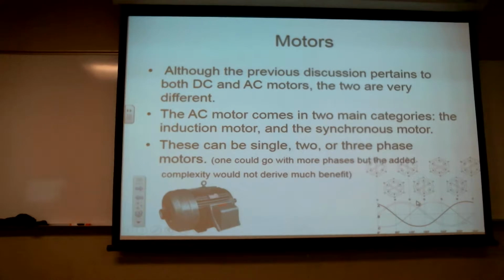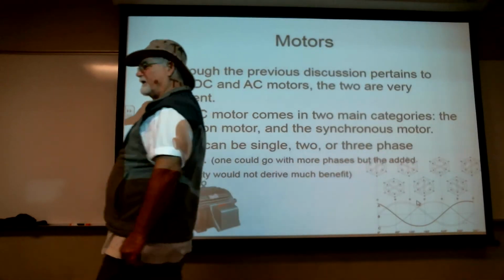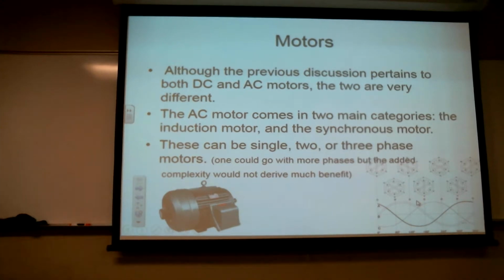Well, the bandsaw is single phase, so that's a different story. Okay, how about the drill? The drill is also single phase. Give me a three-phase out there. The lathe, the mill, the compressor. I forget, there were a couple of the blowers. How do you know they're three phase? The compressor loaded to the side. It just spun backwards.